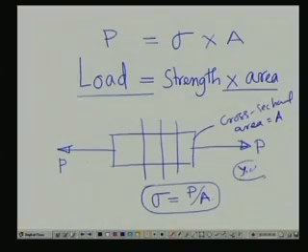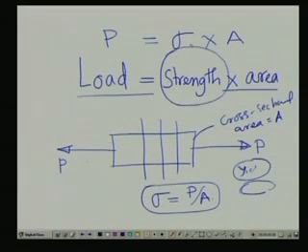Basically it is a failure because it will not come back to its original position. So the yield point is also a failure, and the ultimate point is also another failure we consider. The yield stress point and ultimate stress point are characteristics, as we discussed, the strength of the material. The material fails whenever it crosses the strength of the material, which is a property defined by the yield point or the ultimate point.